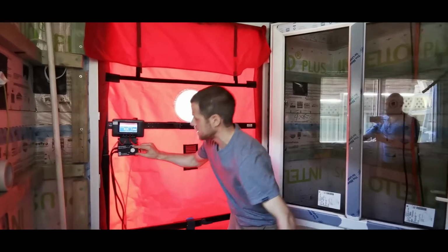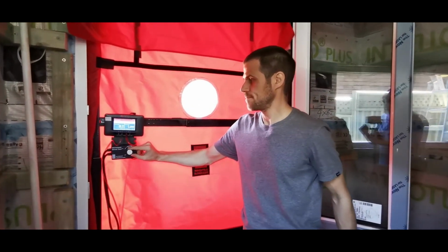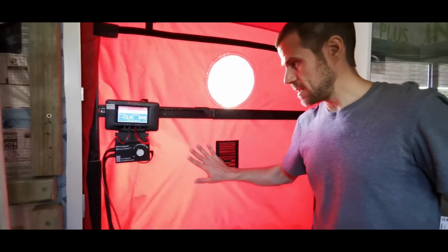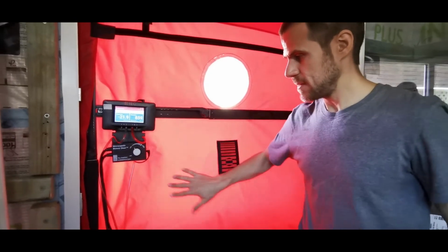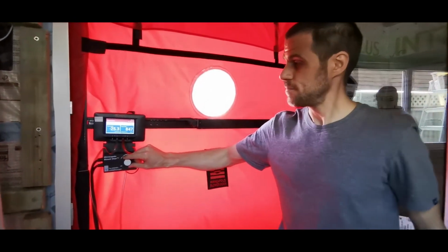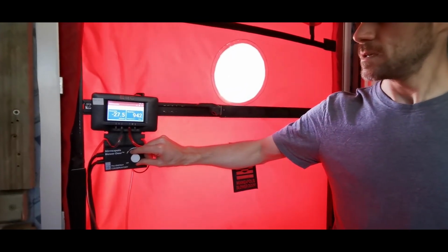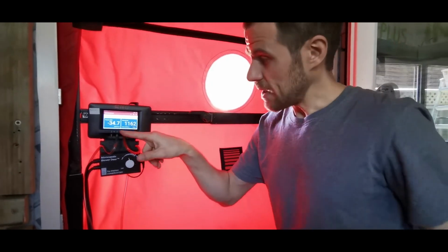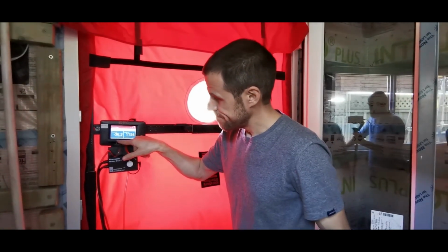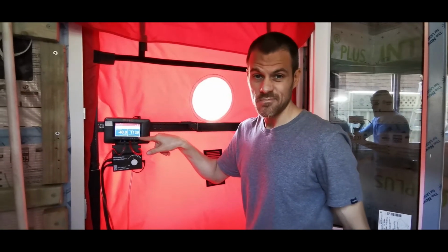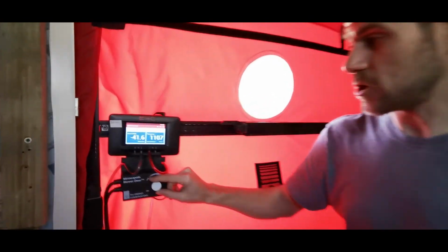So turn this blower door up until it reads 50 pascals, roughly. Let's see what happens. Turn it up. I'm depressurizing, so the fabric is coming towards me. You'll see what 50 pascals feels like real soon. So on the left we have building pressure, 38, 40 pascals right now. And on the right we have the airflow that is required to make that pressure.